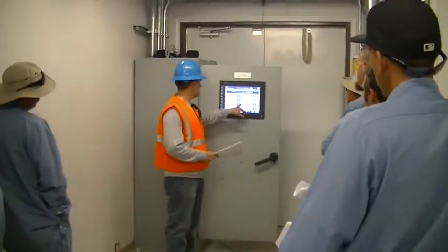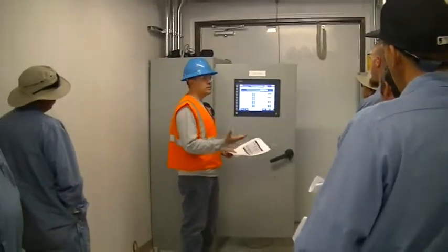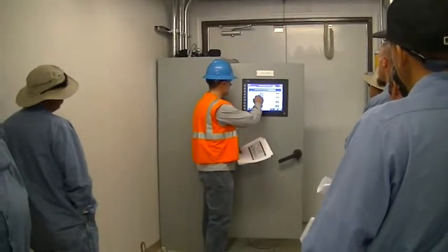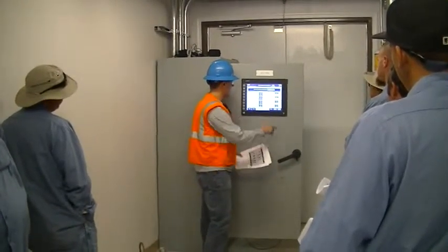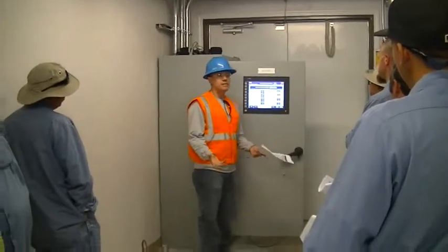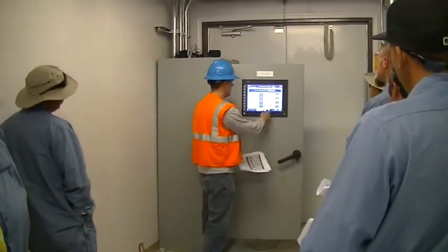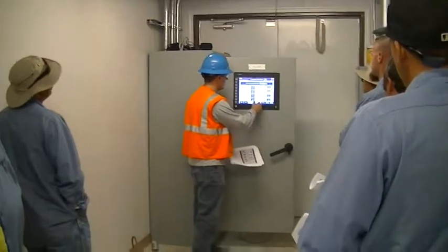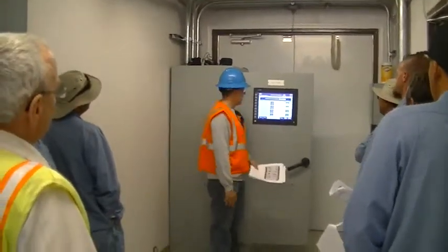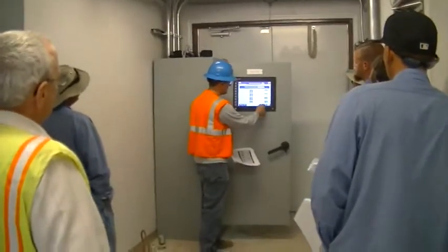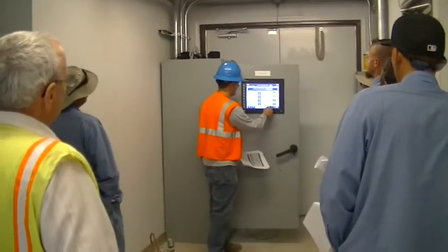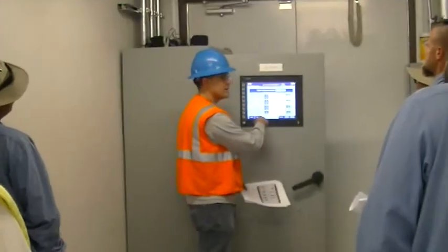So you have your save set points. What you can do is say you change this to the lead start pressure, let's say to 70, and you like that setup and you want to keep that there. It changed there, but you can go to save set points. And then say you're making changes here, and you want to restore all the saved, you just hit restore saved, and it'll transfer them back.